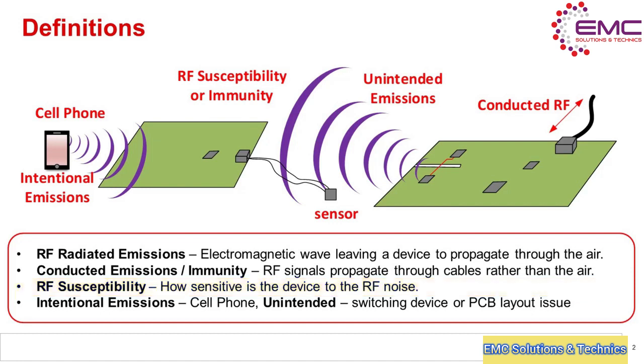the circuit. Finally, it should be noted that some circuits will intentionally radiate, whereas some radiation is unintended. For example, a cell phone is designed to transmit RF signals, so it is an intentional radiator. On the other hand, the digital communications we mentioned previously was not intended to radiate RF noise. One of the main goals of this content is to provide methods to minimize the unintended emissions and improve the immunity of circuits to RF noise.